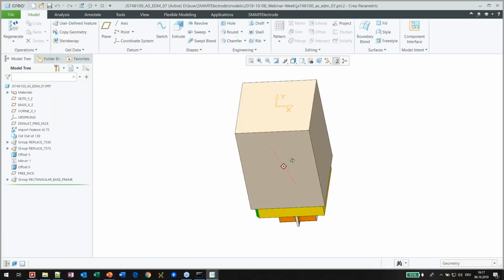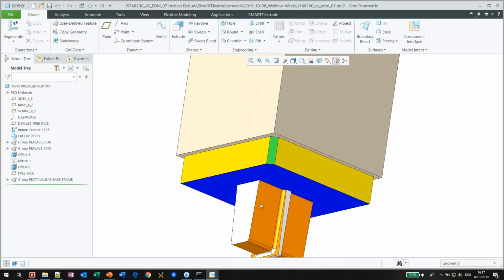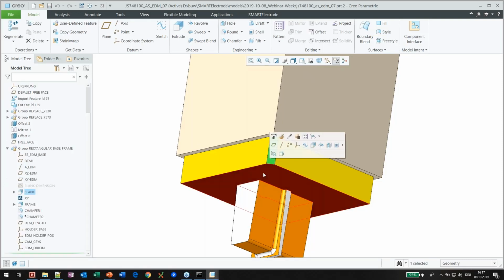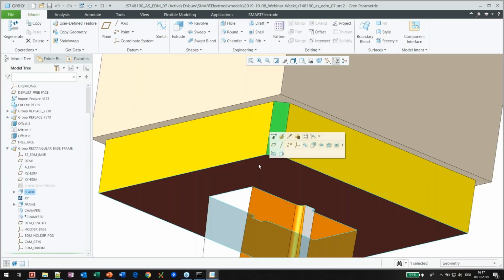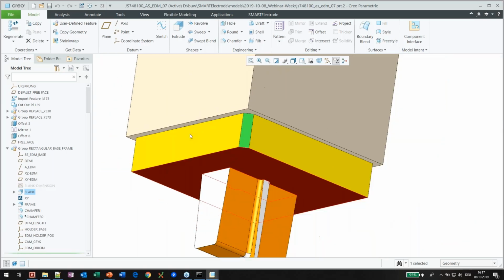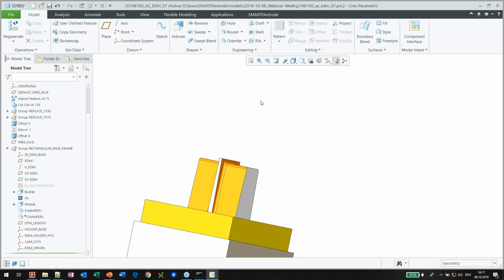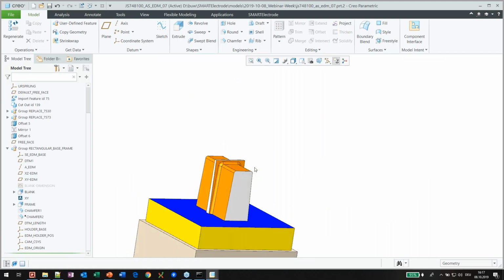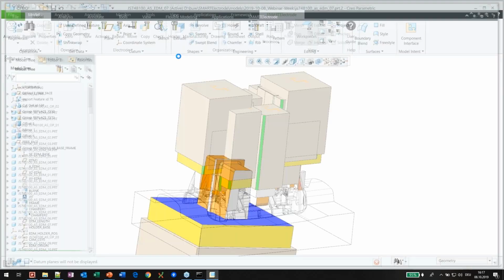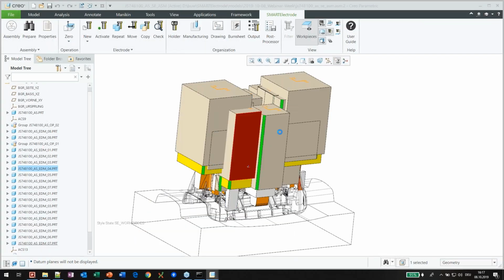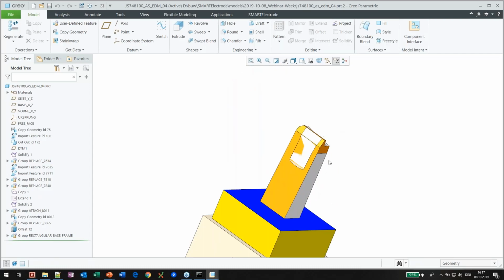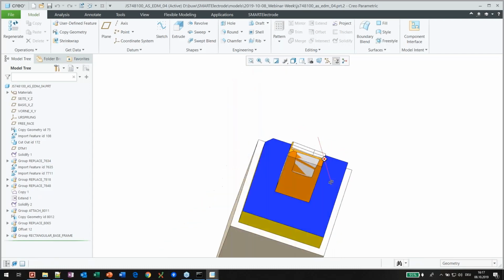So when I open one of the models, we have a specific color code for the electrodes free phase, a specific color code for the orientation chamfer and for the frame. And a color code for all the surfaces the software assumes as touching the workpiece. So the surfaces which would be manufactured. So this is another electrode model with color code.